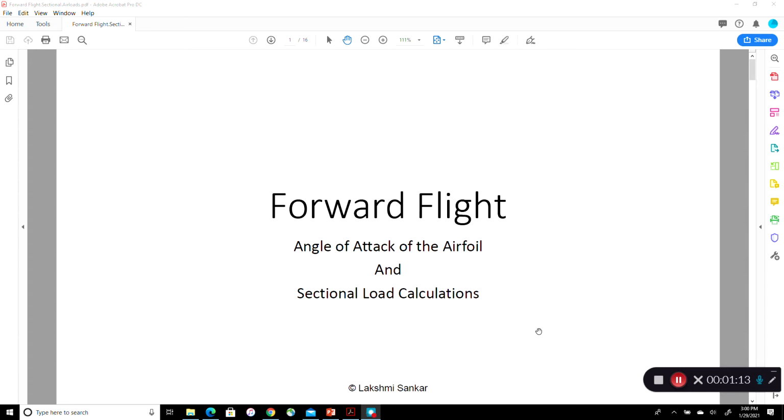So now we are ready to tackle the problem of how much lift is being generated by the whole rotor. A rotor is made of a number of blades. So each blade is divided into small blade elements like we used to do in the past. Then we need to take each blade element, which is a cross-section of an airfoil, plus a small amount of span-wise width or the radial width, delta R. So we need to know how much lift is being produced, how much forces, drag is being produced, and perhaps moments on that airfoil.